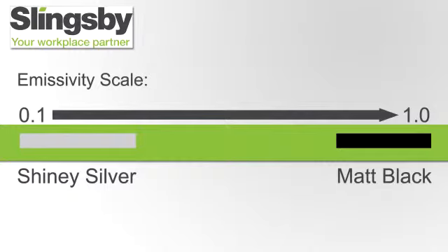Some infrared thermometers feature adjustable emissivity, but it is very difficult for a user to accurately determine the correct value, taking into consideration the whole colour spectrum and taking into account the reflective nature of the intended object to be measured. The error in the accuracy of a measured value can be as much as 30% of the reading, just